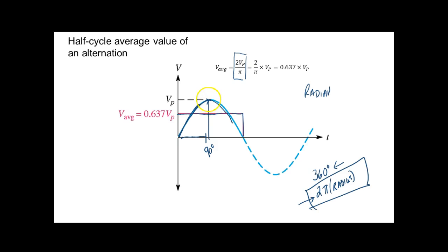So that means if I came over here and this was 10 volts, and I had the ability to measure that DC average right there, then I would say, okay, the average voltage for that would be what? 2 times VP divided by what? 3.14. In fact, I would use 3.14. If you use the pi key on your calculator, you're a heck of a lot more accurate than you need to be.